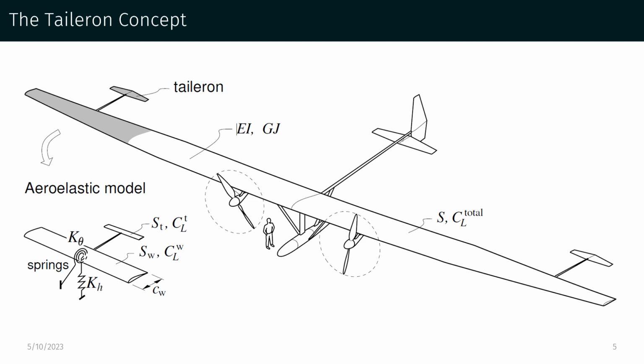They provide three main functions. First, they suppress torsional divergence by neutralizing the wing's pitching moment. Secondly, they replace ailerons for roll control by twisting the wing, essentially wing warping. Interestingly, this avoids control reversal that plagues conventional ailerons because you're effectively always operating in a fully reversed condition. Thirdly, they add considerable pitch damping because of the relatively long moment arms.